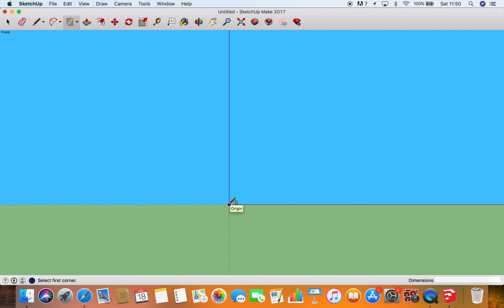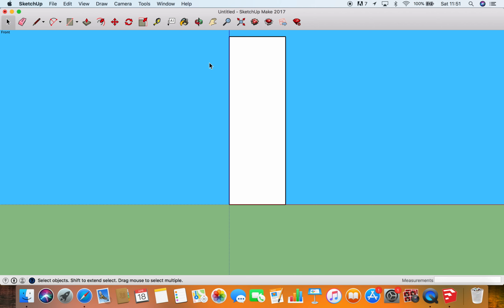I click once, okay? So it then extrudes this rectangle. This rectangle is going to be our drawing pad for the moment. So I'm just going to click about there. Also, once I was selecting and drawing the object out, I could have locked that to the axis. I didn't need to because we're in this parallel projection mode. So I'm just going to hit spacebar again to get back to our normal arrow. So I can select this, okay?